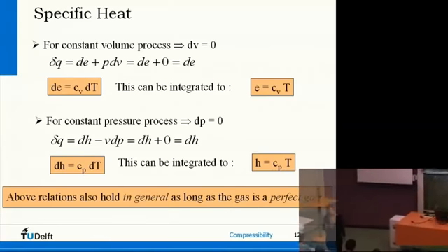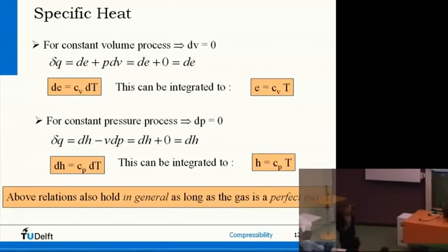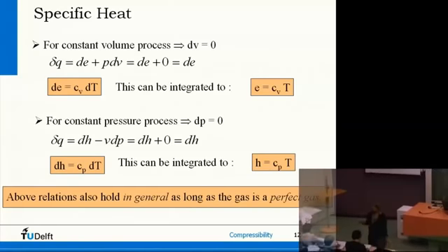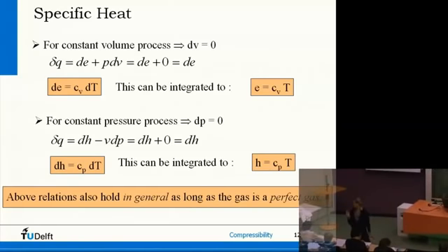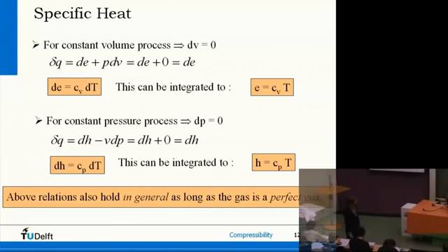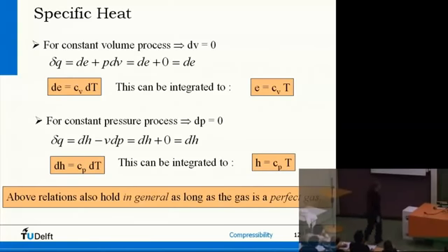So I have a direct relation between internal energy per unit mass and temperature, and it's linearly related, and the only thing that's in there is the specific heat at constant volume, so Cv. Now I play the same game, but with a different relation from the first law, where I didn't have dVs, but I had dPs. And of course I play the game now for constant pressure processes, so my dP is 0.